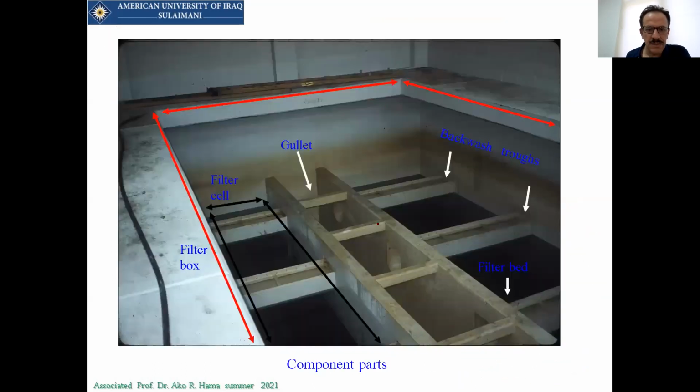Yes, this is the top view of the channel. This is the filter itself, and the gravel and the sand will be put here. When you want to wash the filter, the water comes up this way from the inside. It will get inside and be collected in these troughs. These are channels, and then it will be collected here and drained out.